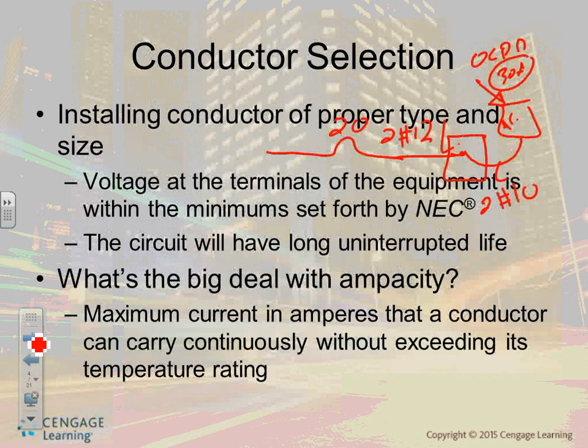Same thing for three-phase equipment, guys. You're going to see an air handling unit, and on it you're going to see it needs three-phase 480. Okay, do I need a neutral? No, you don't need a neutral. Almost all three-phase equipment does not need a neutral. Okay, so that's basically what needs a neutral and what doesn't.